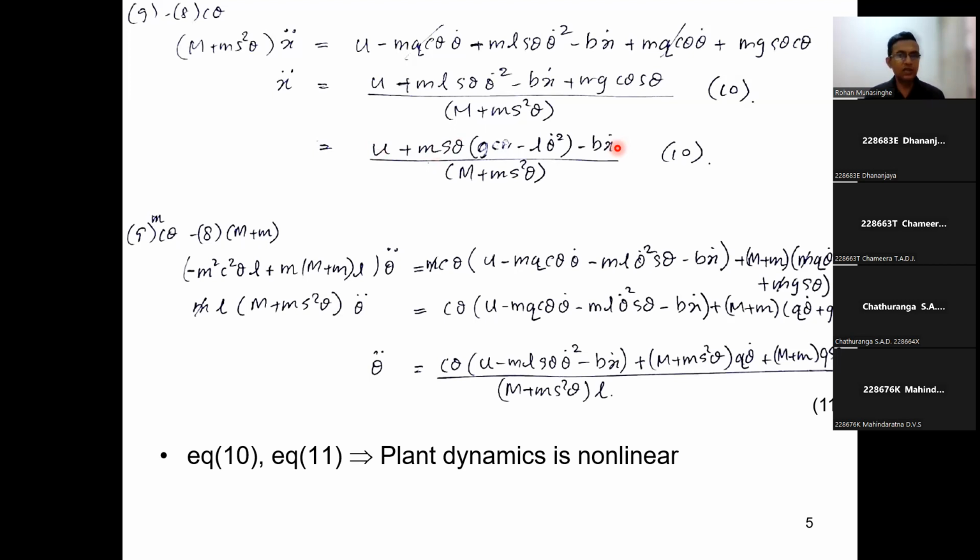Okay, but the good thing is that you know this complicated relationship now, so that you can go to MATLAB and program it if you wish. So that is about x double dot. This is the highest derivative of x. Now, if you know how to calculate this, you can update x dot, and then you can update x. You can update the position of the cart. You can actually simulate the motion of the cart, x dot, x double dot.